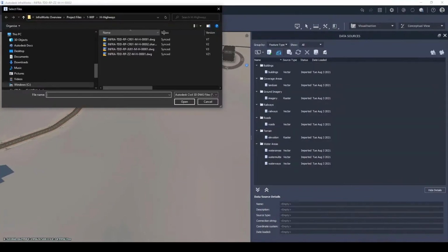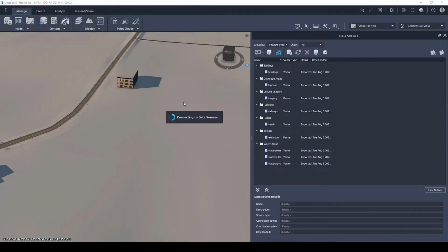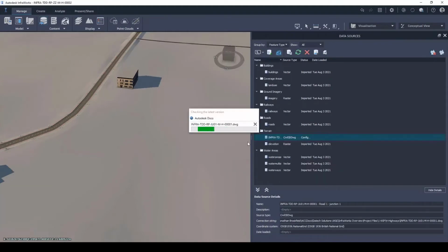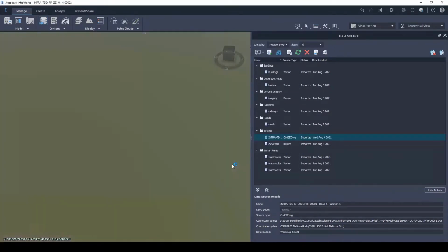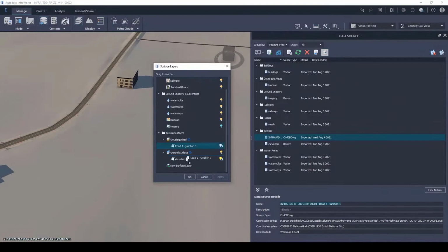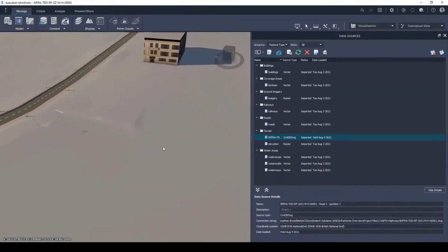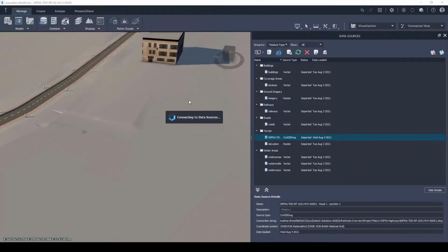Inside of our InfraWorks model, we have the ability to import a proposed or more detailed topographical Civil 3D surface. The elevations from the Civil 3D surface will replace those found inside of InfraWorks using a hierarchy, triangulating between the two terrains at the tie-in boundary. This allows designers to quickly present their proposals in context and append other discipline models such as structural steelwork, architectural building shells, and so on, aligned to new ground levels.